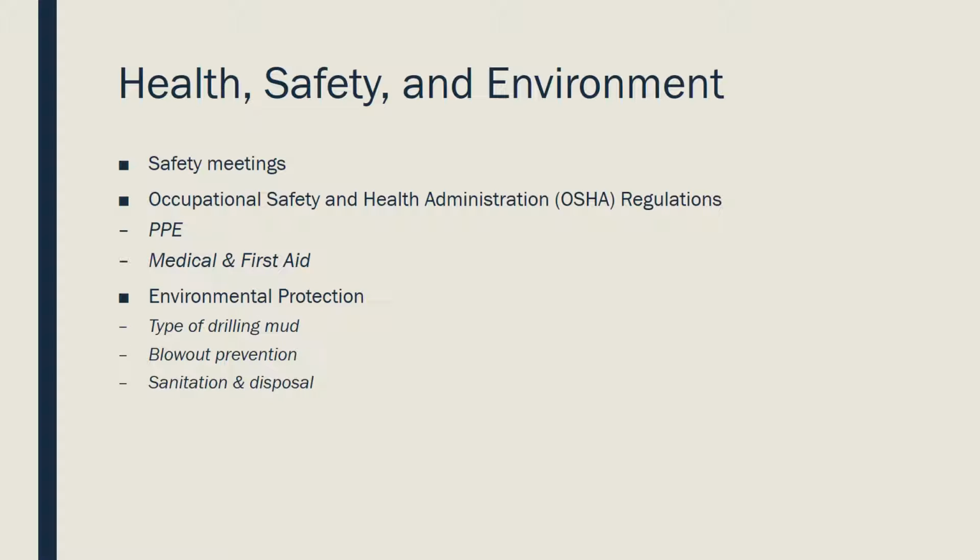The most important aspect of drilling a well is maintaining safety on the rig. Pre-tour safety meetings will be held at the beginning of each shift in order for the crew to be familiar with what happened on the previous shift and what is to be expected during the upcoming shift. We will also have to maintain OSHA regulations throughout the entire drilling process, such as requiring personal protection equipment to be worn, presence of safety signs and accident tags, fall protection, proper ventilation, means of egress in case of emergency, and noise exposure. Environmental protection should also be kept in mind.